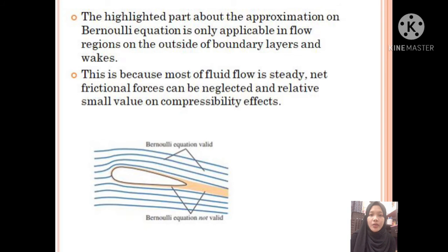Another point about the Bernoulli equation is that it uses approximation in its derivation. This is because most fluid flow is steady, net frictional forces can be neglected, and compressibility effects are small. As shown on the slide, the Bernoulli equation is only valid in the region outside of the boundary layer and wakes.